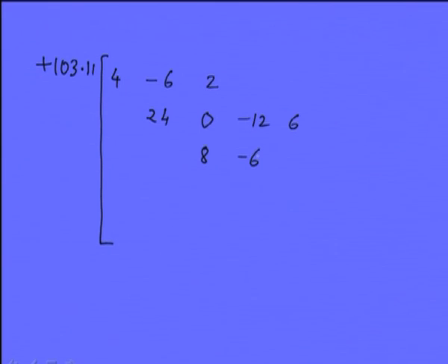Similarly, we will have the stiffness matrix, that is the reduced stiffness matrix. I am writing it by elimination of the first row and seventh row, and we are adding all the terms which came from various elements.